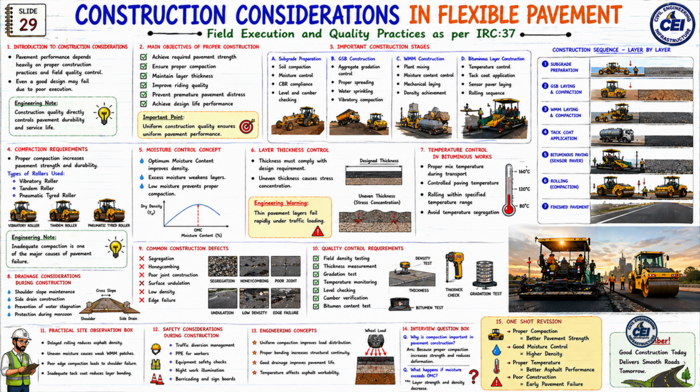Quality control requirements. Ensure construction quality. Field density testing. Thickness measurement. Gradation test. Temperature monitoring. Level checking. Camber verification. Bitumen content test. And these tests are mandatory in highway projects.